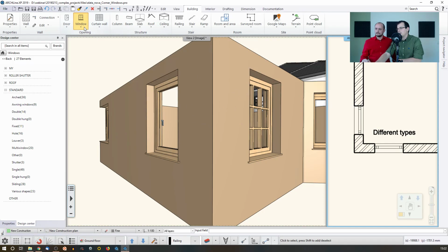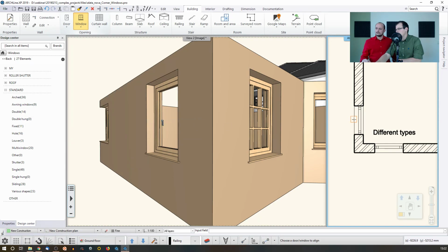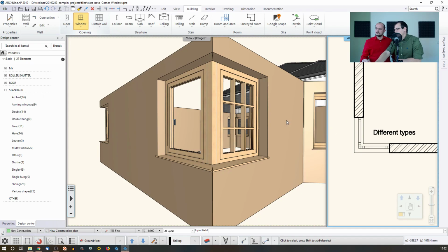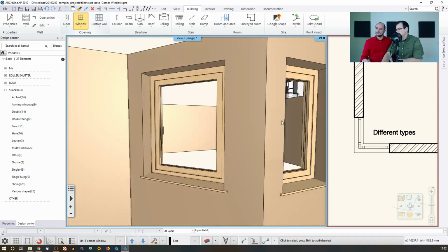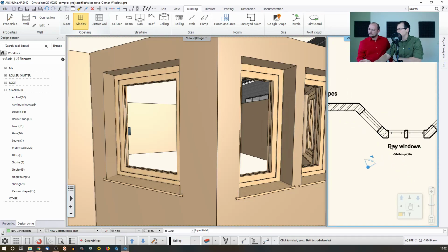If you have a sash window or anything like that, you can just again use this tool over here or from the local menu and link them up. But now comes the tricky part, and that's a recurring topic, especially for buildings in the UK and in other places as well. What happens with bay windows? Because bay windows meet at an angle.